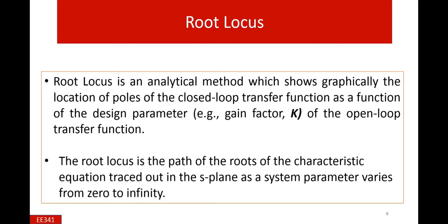If we set this characteristic equation equal to 0, we can find the roots of the equation. There is a dynamic parameter, usually K, and if we change K from 0 to infinity, actually not infinity, close to infinity, or from 0 to some maximum value, then the roots of that equation, which may be of any order, change accordingly. This is the root locus.